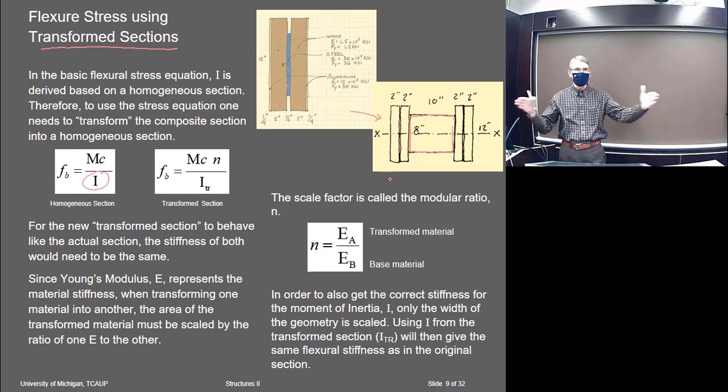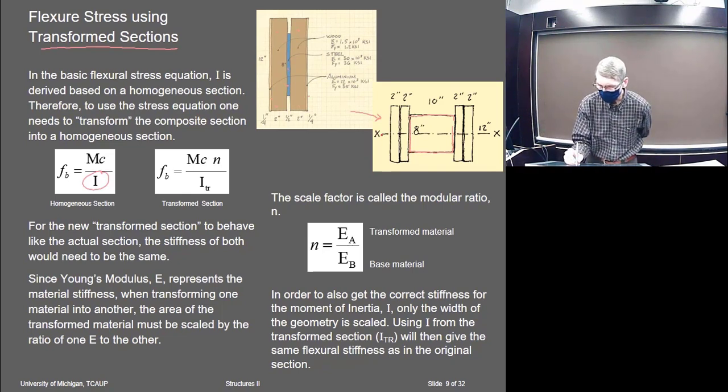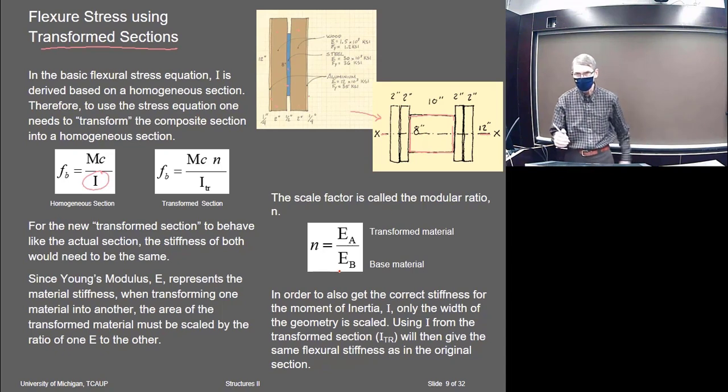So I change the thickness because I'm going to take the moment of inertia about that axis. If I change the depth of it as well, then that would be adding another component to stiffness, right? It would be getting stiffer because of the depth. So I don't want to do that. I just want to keep it linear, and I just add the thickness in the direction that's along the axis, parallel to the axis, I guess.